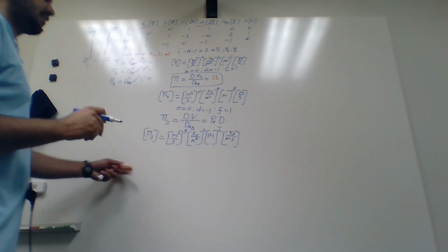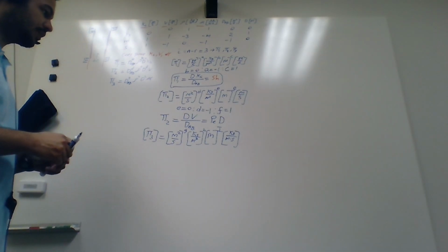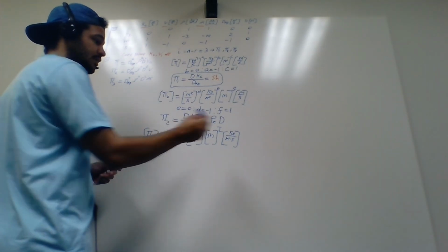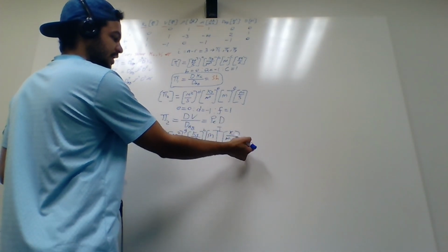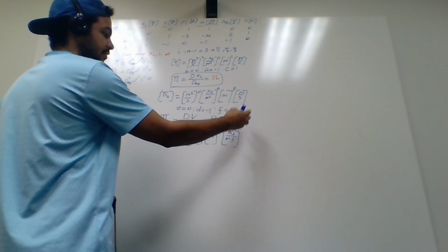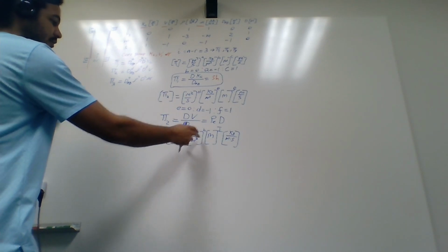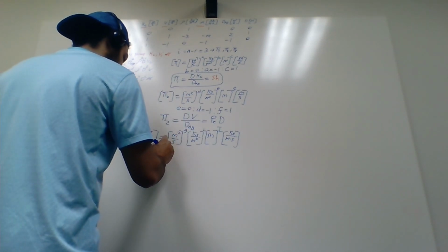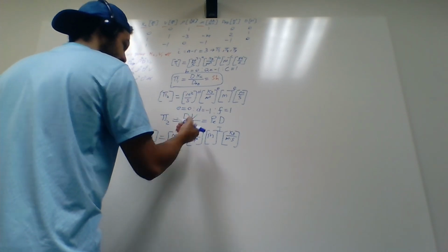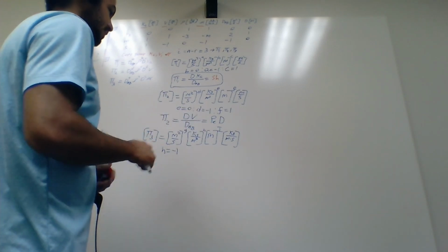And now all the units have to cancel out. So in order to cancel out the units, we know that the kilograms must cancel, and since there's no power here, we cannot determine if this viscosity must always be on the numerator. So looking at the density, we can determine that that is on the denominator, making H equal to -1, which then allows the kilograms to cancel out.